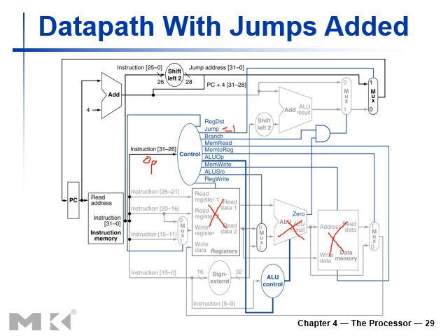All right, and now what we have to do is extract those 26 bits and then convert them into 28 bits, and then concatenate that. So what we have done here, if you see that we are using this line, these are the 26 bits of the address multiplied by 4. So we are using shift left 2,